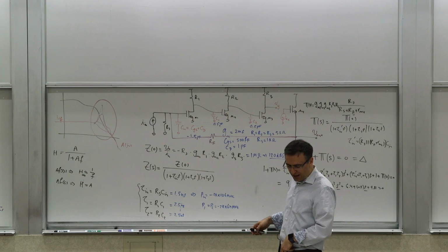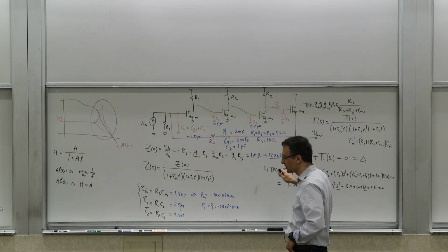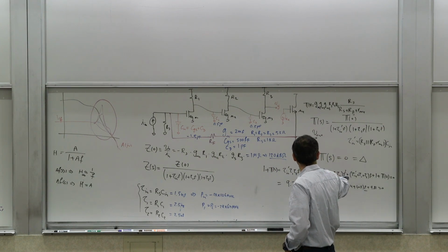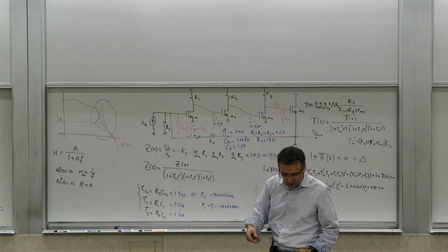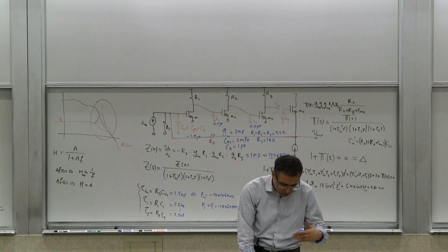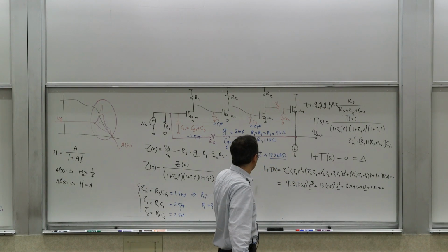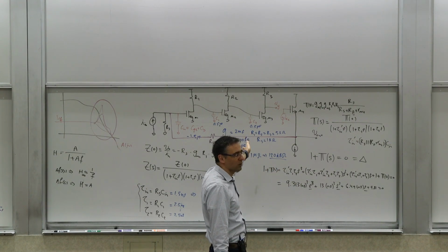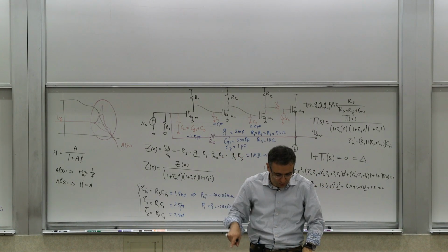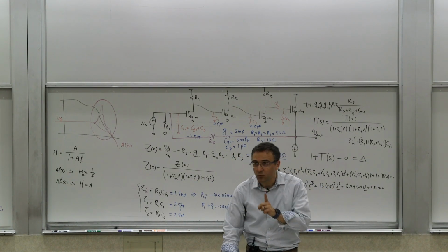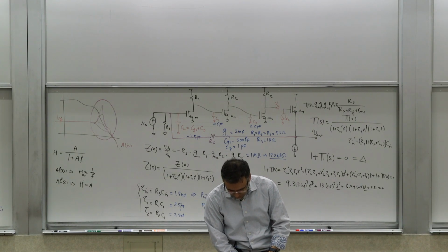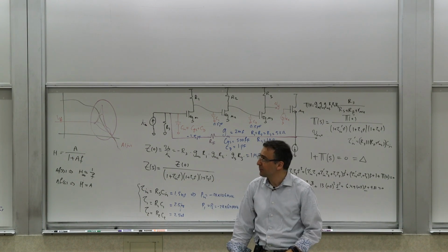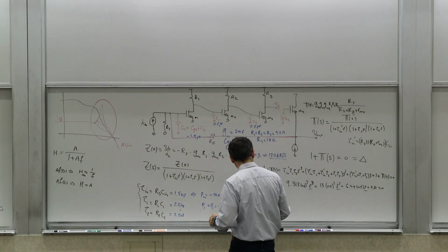So in this case, if you actually find the roots, you can find where things are for different values of t0, etc., and then you can find where the poles are. You will see that in this example, for the values that we had, you have two right half plane poles, which is what produced those sinusoidal responses. Now, we will make one change to the circuit. And that's actually the part that makes it quite interesting.